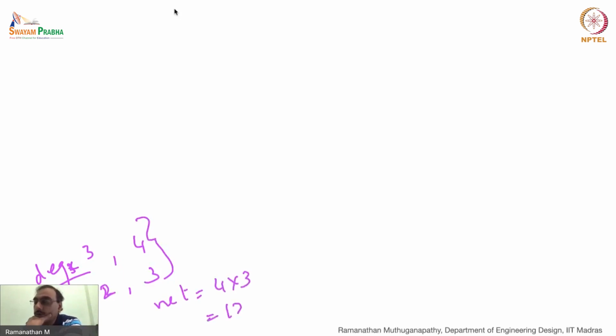So you need 12 control points, which is called a control net, so that you can actually get a Bezier surface, which is 4 by 3. That means you can have degree 3 in one direction and degree 2 in the other direction. Okay, how does that work?